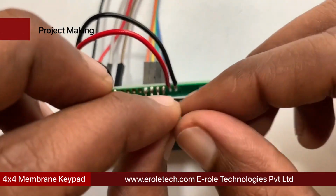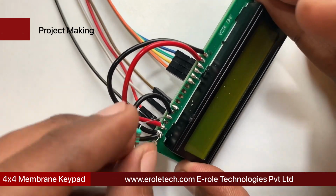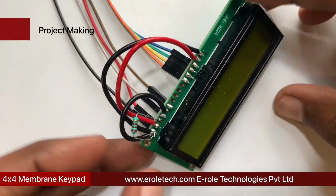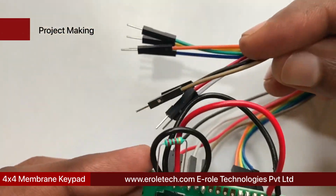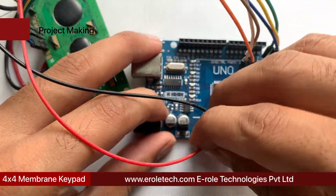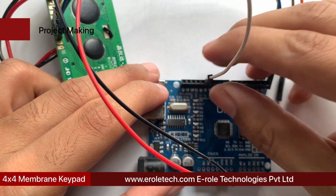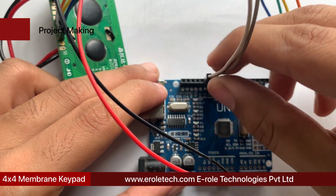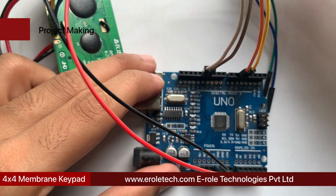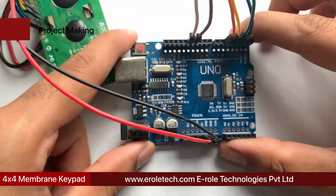Now connect hole number 5 with hole number 1 of the LCD display using a black wire. Now connect hole number 3 with hole number 1 of the LCD display through a 1 kilo ohm resistor. Connect the red wire with the 5 volt pin and the black wire with the ground pin. Now connect the white, brown, orange, yellow, green, and blue wires with pin numbers 12, 11, 5, 4, 3, and 2